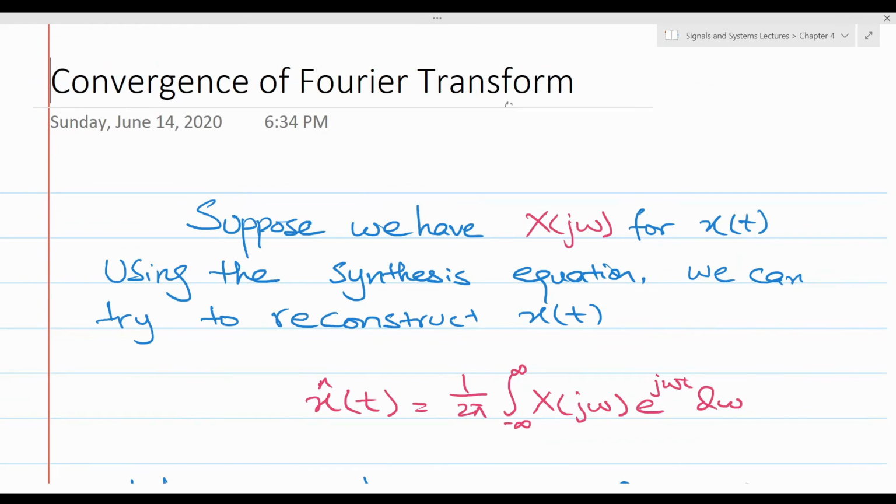When we learned about the Fourier series for periodic signals, we saw that the Fourier series does not exist for all type of periodic signals. For the best Fourier series representation of the periodic signal, the periodic signal must satisfy some conditions which were called Dirichlet conditions. Similarly, for all the aperiodic signals, Fourier transform does not exist. So in this topic, we will learn which type of aperiodic signals will have its Fourier transform.